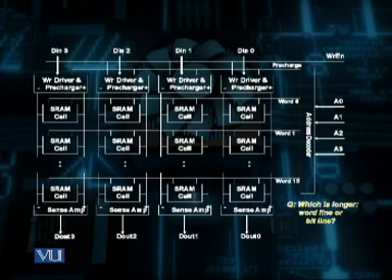But for the bit lines, we still have to rely on the tiny transistors of the static RAM cell. That's why we need to pre-charge them to a high and use sense amplifiers to detect the difference.